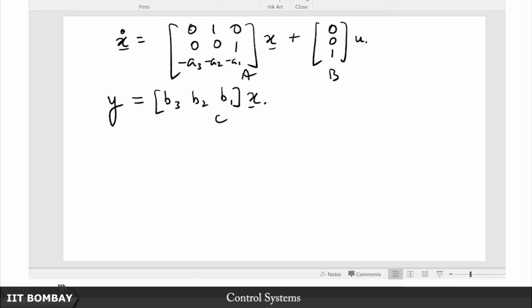So now where are we currently? Again, to take stock of the situation, we have seen that there are these states that allow us to have internal descriptions. We have seen that given a transfer function or an ODE, how to get this state space representation by drawing either the block diagram or by doing a bit of algebra with the so-called phase variable form of the state space representation.